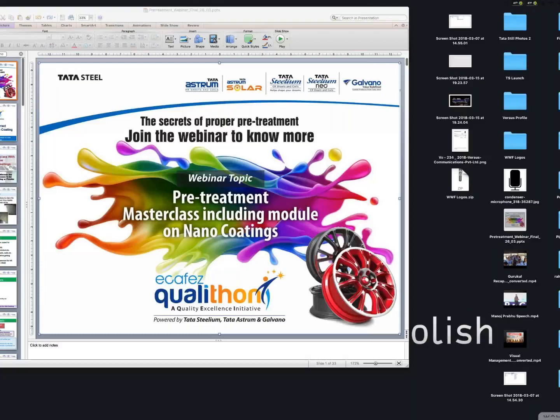Mr. Shaktivelan asks, what are the probable reasons of failure of the degreasing process that can result in field failures after 4-5 months of usage? Sir, basically not getting your oil cleaned is the main reason. That's all. And there may be various reasons because you might not be having correct pointages.